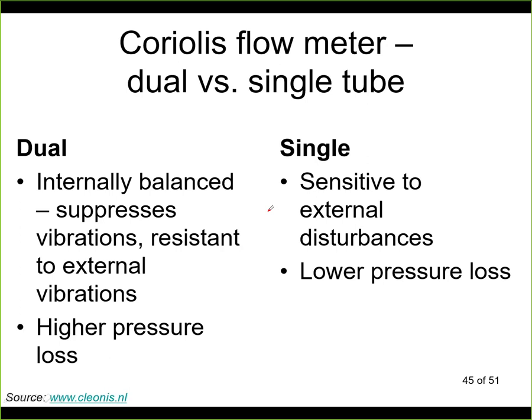This is the comparison of the dual and single tube version. I've already explained that. The dual has a little bit higher pressure loss, but it's not sensitive to external vibrations. Here we have the sensitivity to vibrations, but we have a little bit smaller pressure loss.